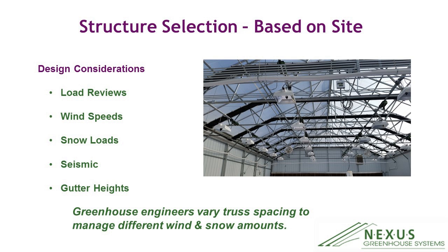That's correct. And then also, when we talk about these live loads, wind, snow, and seismic, we have to think about our dead loads too. And so a cheaper structure, say for example, bent tubing for a high tunnel structure, kind of a ground-to-ground, that's probably not going to be able to pass any kind of code for supporting all the different dead loads that are inside the greenhouses, such as lights and heating and cooling equipment, and then also the shade system. So when we're talking about load reviews, we're talking about both live and dead loads, and the live being the wind, the snow, and the seismic, which really requires an engineered structure in order to take on those kinds of forces. Great. Thanks for bringing that up.